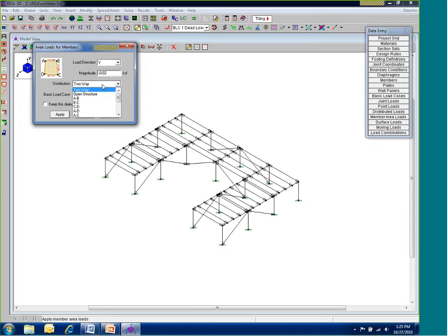And now you have a couple options. First thing we're going to see here, you have a two-way, which will distribute the loads in two ways, meaning in different directions. If we were to imagine, it would go in all directions, so a two-way makes sense like that. In A, B, that's the way I'm going to click the button. So we'll see here, if I click from A to B, the loads are going to be distributed in that direction. So I'll show that, and that's the best way to see it, is how it actually gets distributed.